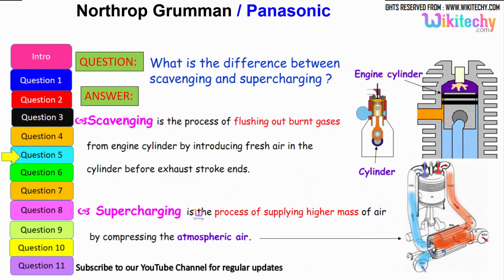Let's move on to the different question. What is the difference between scavenging and supercharging? Scavenging is the process of flushing out the burnt gases from the engine cylinder by introducing fresh air in the cylinder before the exhaust stroke ends.